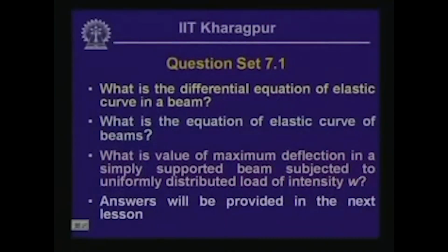Now, these are the questions set for you. What is the differential equation of elastic curve in a beam, what is the equation of elastic curve of beams, and what is the value of maximum deflection in a simply supported beam subjected to uniformly distributed load of intensity W. Now, answers for this I will give you in the next lesson.